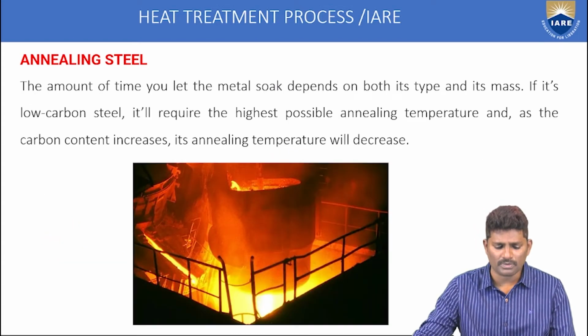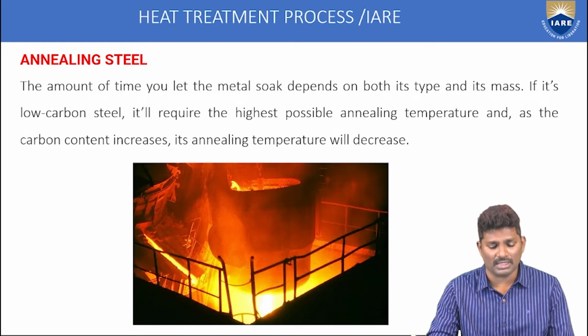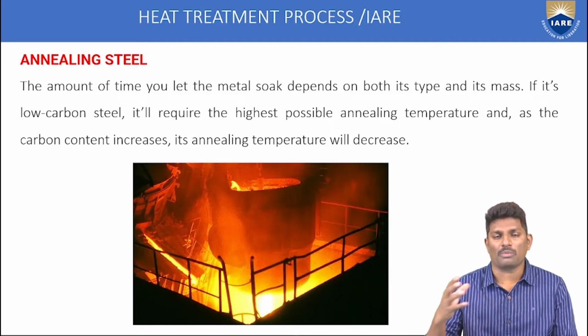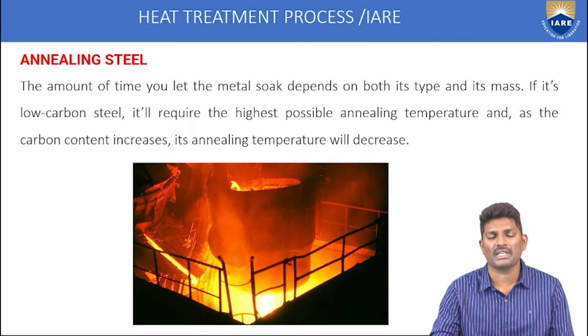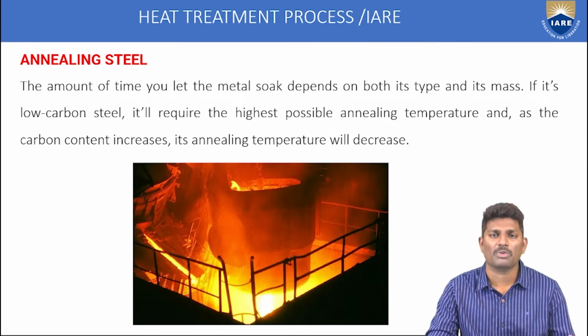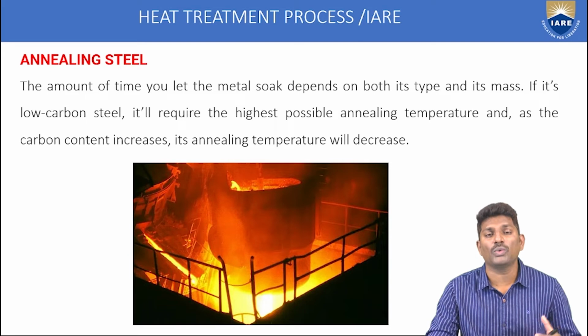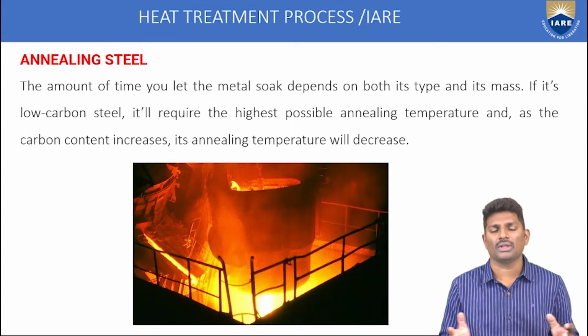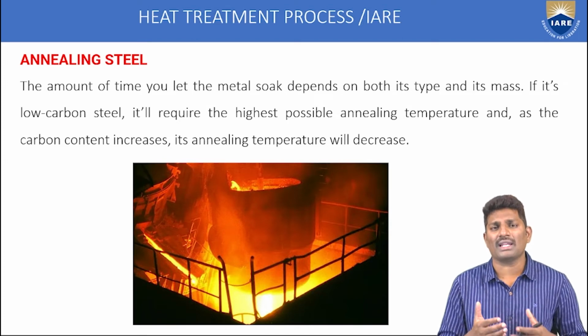The amount of time you let the metal soak depends upon the type of material and its mass. Each individual material has its own mechanical and physical properties. Depending upon these properties, the time taken to cool the system depends on the material and also its mass. If you consider a small mass or less weight of material and try to cool it down, it will take very little time. But in the same way, if you take a large mass, it will take a longer time.